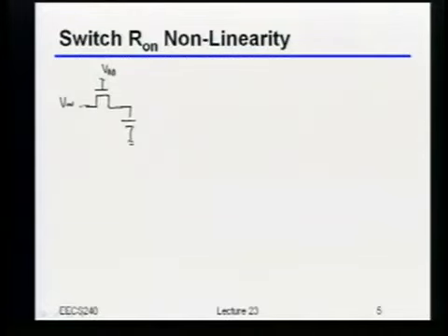Ah, well, okay. So let's assume I really did it this way. And what I'm really interested in is while the switch is basically tracking. In other words, I've just got it like this, the gate's at VDD, Vin is at whatever it is, and I just have a capacitive load at the output. What region should that switch be operating in? Linear, right? Yeah, it should be in linear.